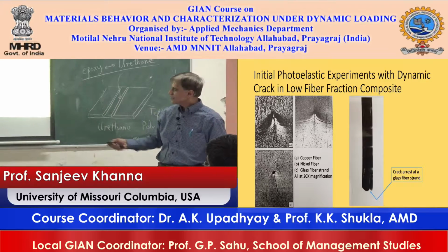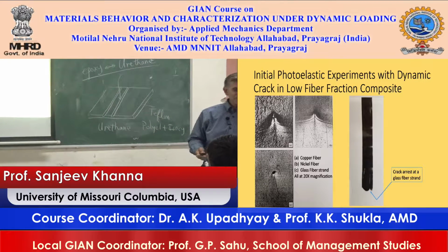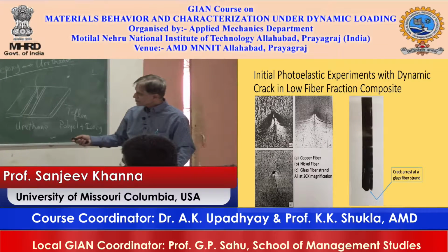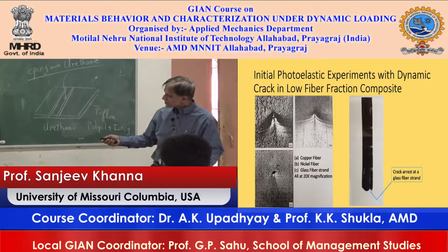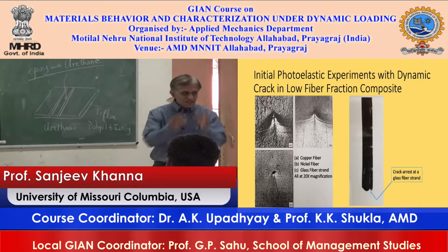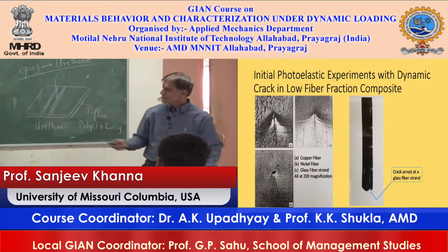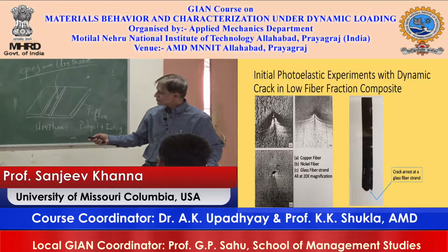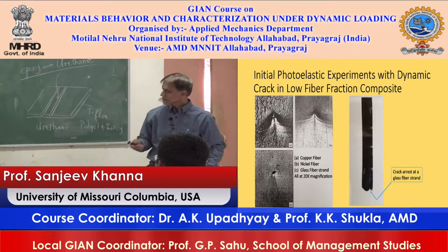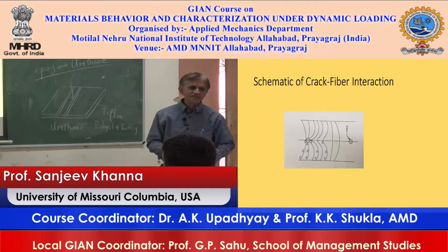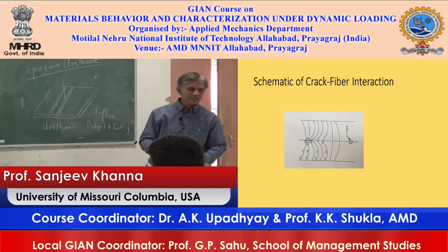Look here. We were able to capture one picture with the high-speed camera we were using, where you see that this is the fiber and this is the crack front. See how it is divided into two crack fronts. And these are the fibers, one here, one here, here. So this is schematically how the crack is propagating around the fiber.